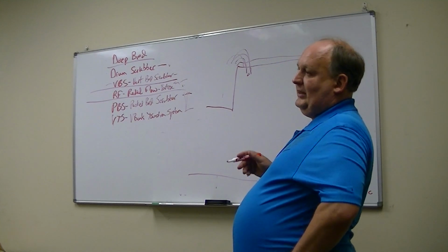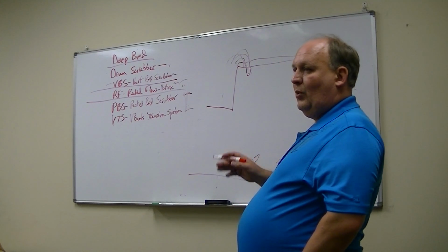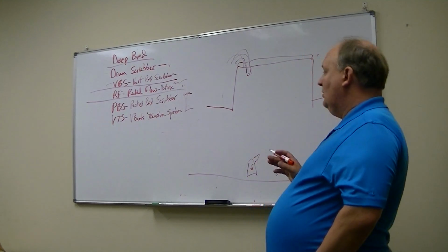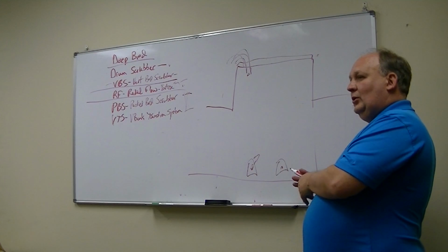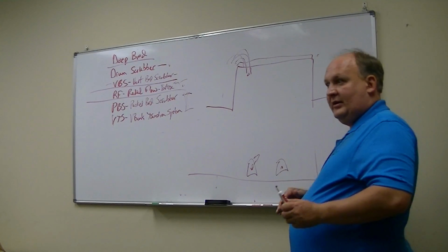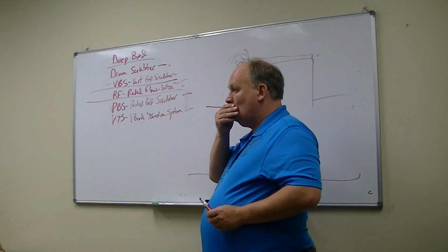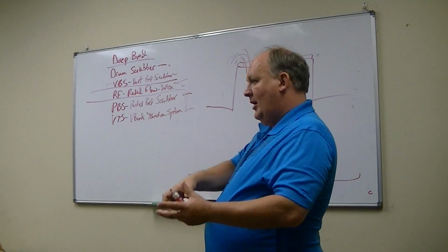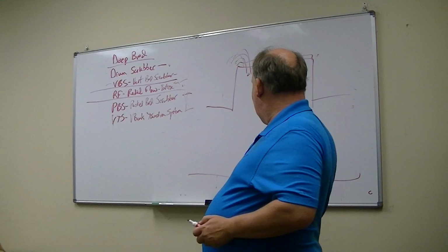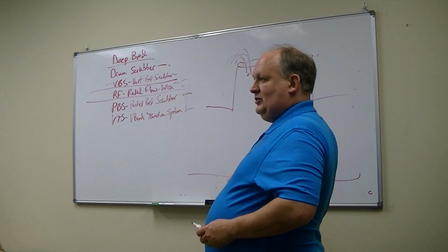So we have to be careful because our sales drawings still show the vacuum ports and things like that, so we just need to make sure, if it's required, if it was in the sales drawing, we need to include it, but we ought to start taking it out of the sales drawing. The vacuum port, is that a quick connect? A quick disconnect, yeah. Thank you. You take off the quick disconnect, you hook up a 6-inch hose to it, and then you turn on the vacuum and it sucks the carbon out.